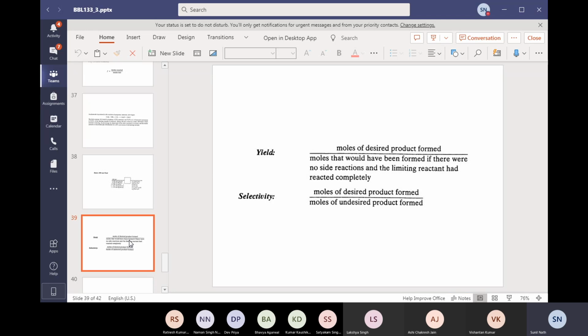That is our yield based on feed. The second definition, which I am also all right with, is the yield coefficient or percentage or fraction, yield based on reactant consumption. So this we define as moles of desired product formed divided through by moles of limiting reactant consumed.